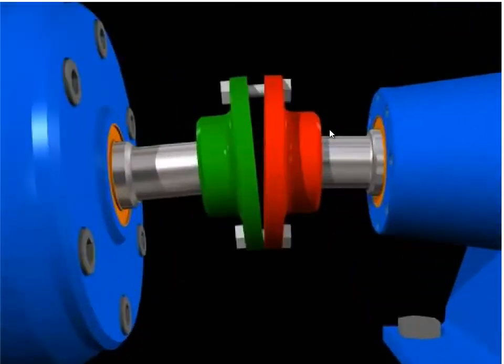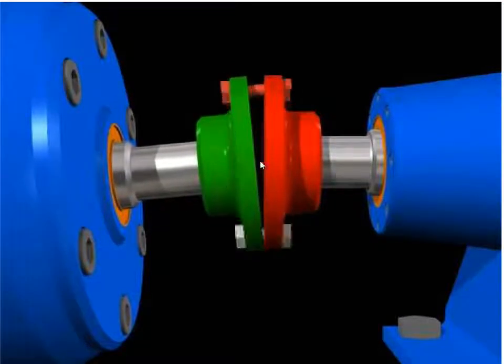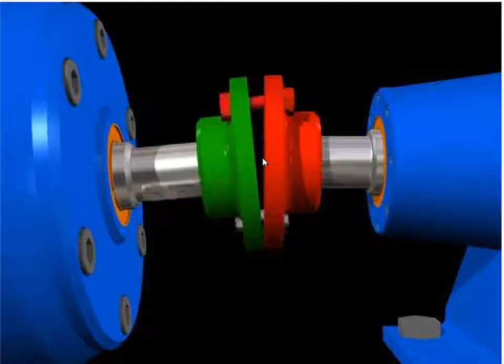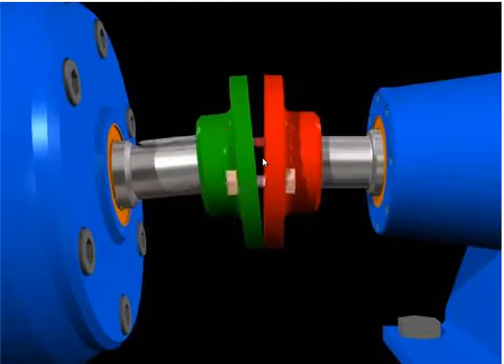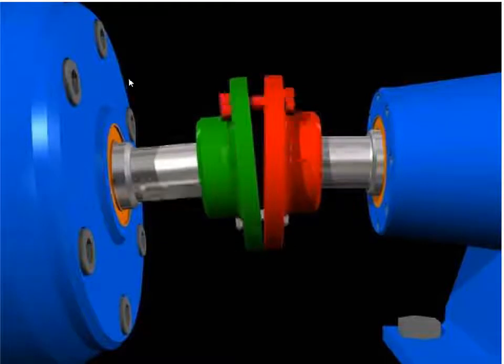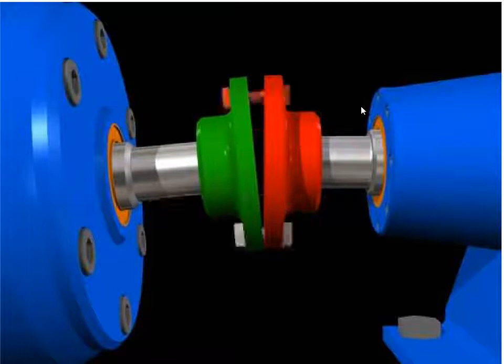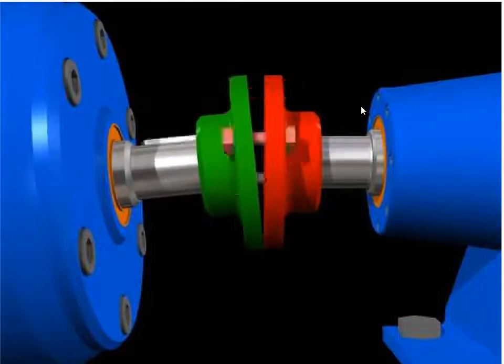With angular misalignment, not that you can see it, ignore that key, it's like pushes, pulls. We get axial vibration and we see a phase difference between this face and this face. We have to adjust them because we're pointing the sensors in opposite directions, but we will see that 180 degrees phase difference there.